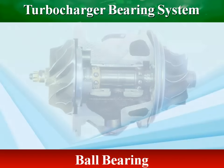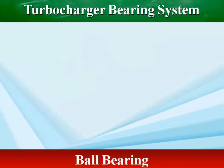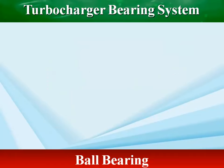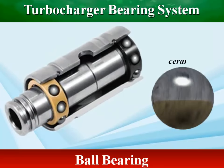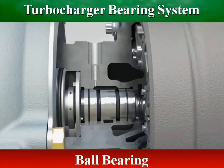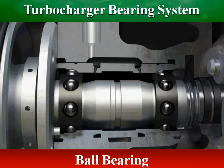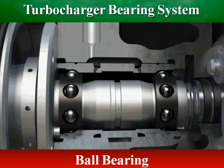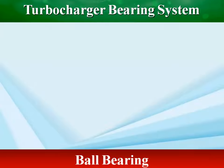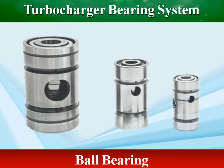Ball bearings combine the functions of journal and thrust bearings into a single package. Ball bearing designs require less oil consumption than journal bearing designs. Ball bearings utilize a system of balls, often ceramic, and races to achieve lower friction, faster spool-up, and improved performance. Ball bearing turbos are often used in high-performance or racing purposes where quicker spool-up and better efficiency are critical. The design of ball bearing turbos involves more complexity, and is therefore harder and more expensive to rebuild.